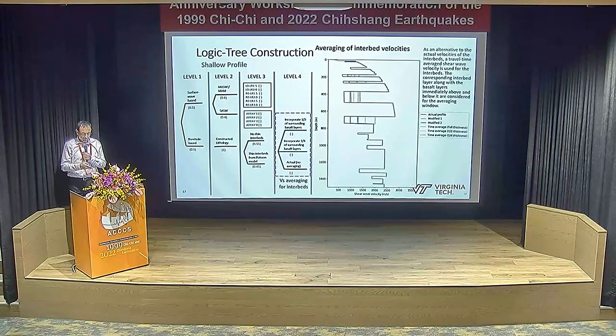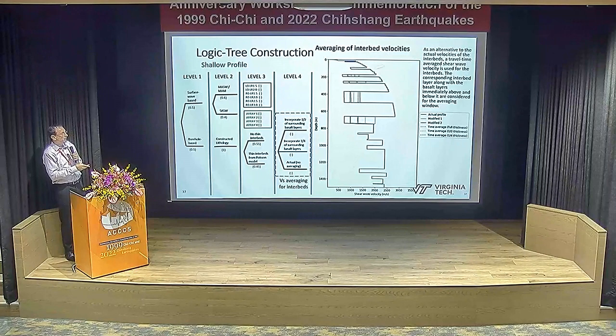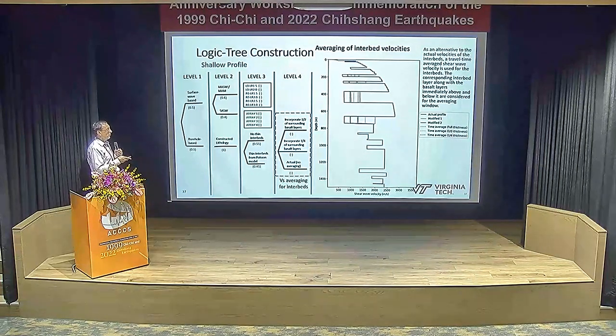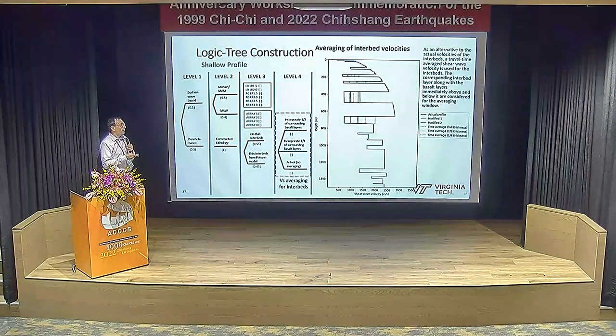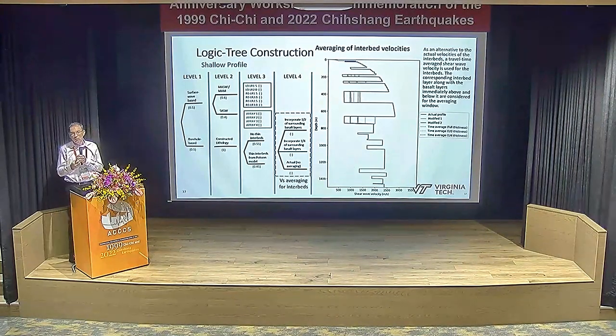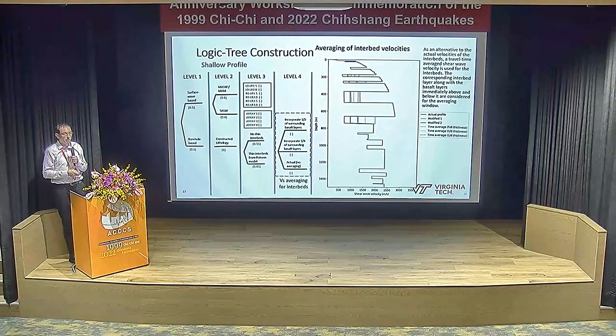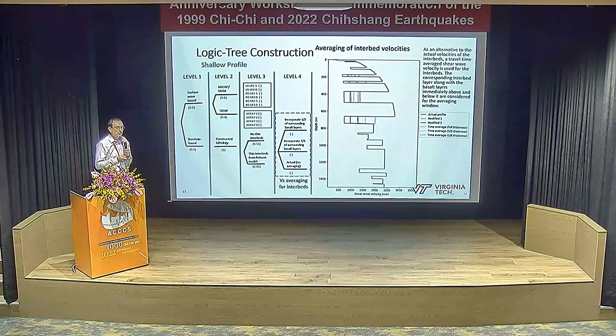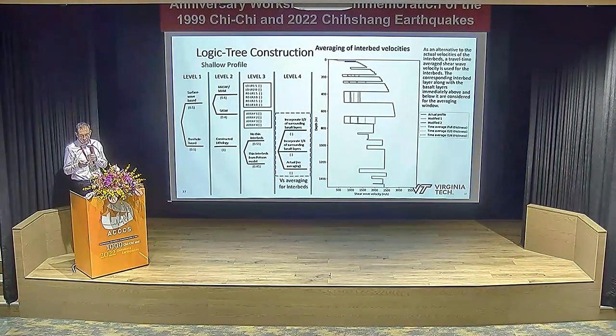This is a typical profile on the site. You can see these interbeds. These interbeds, strangely, or maybe not strangely, at least it was a surprise to us, had a very strong impact by introducing a significant degree of attenuation across a broad range of frequencies. So we were a bit suspicious about how much attenuation these interbeds were introducing.